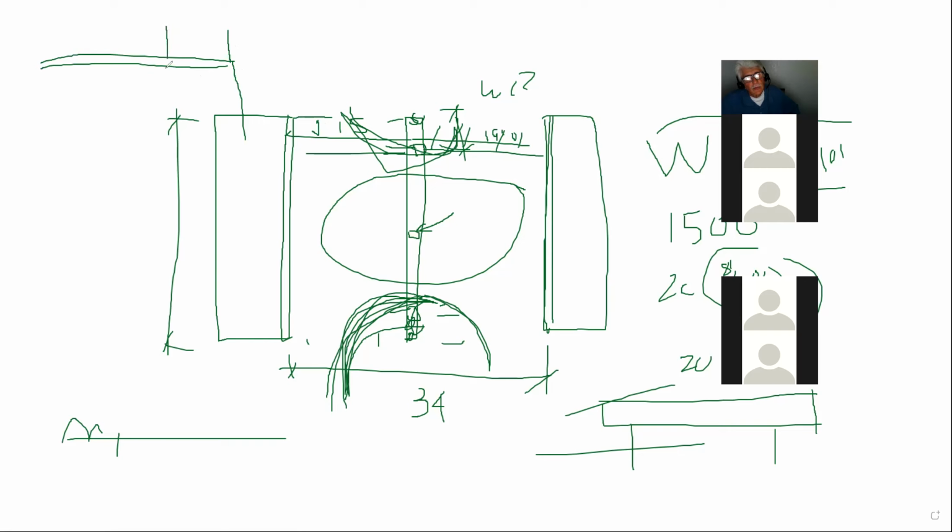if you let the stud in the wall fall right underneath the roof joist, you don't have to double your plate. He said, yeah. And even the code says that if the stud in the wall falls directly underneath the joist, you don't have to double your plates. You're going to save yourself 80 feet of 2x4 just on the top plates. You understand? So he said, oh, great. Okay, thanks. So I did everything.